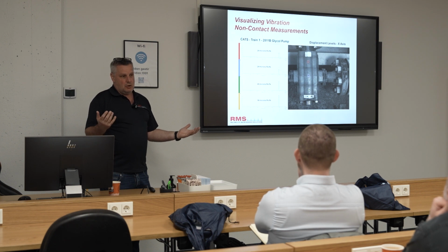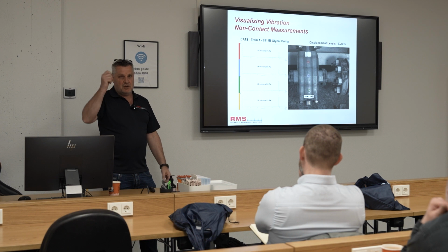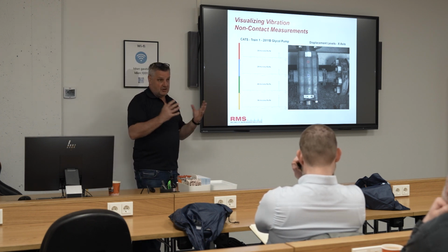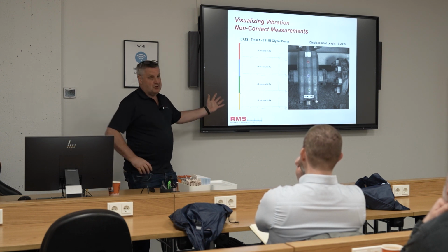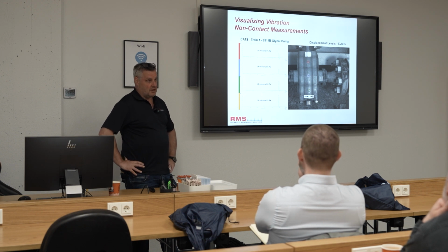Now, this is where it's so powerful as a tool. We can take vibration measurements of pipework across welds and reflect that against the Energy Institute guidelines for an ISO tolerance, and give that to a manager saying that pipework is out of spec across those welds. But if you show them a picture, the video is so much more valuable than information written down like that.